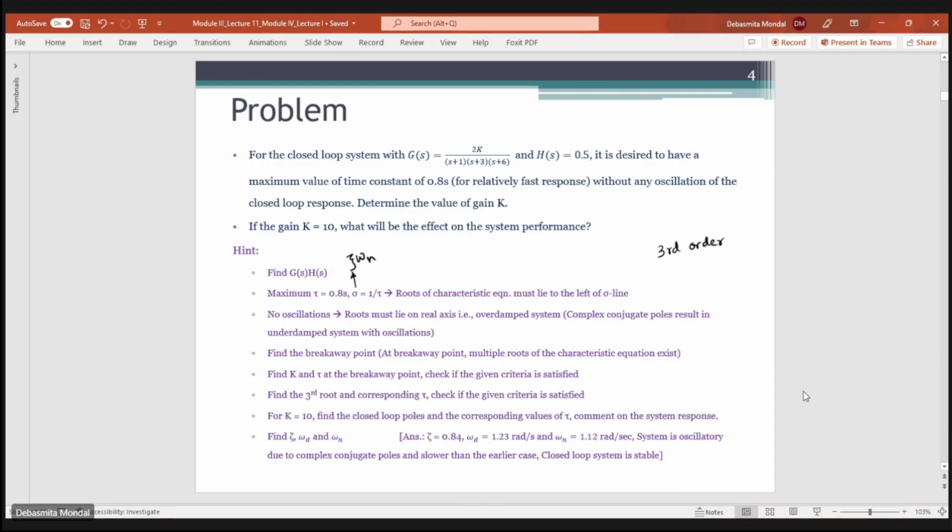So this is very important, because if you look from a practical point of view, whenever an engineer or a designer is trying to develop a control system, they know what the desired response needed for the system will be. Depending on the nature of the desired response, you have to design your control system in such a way that you adjust the values of the poles and zeros, the value of the gain, and if you have some other parameters, you adjust everything according to the given system specification.